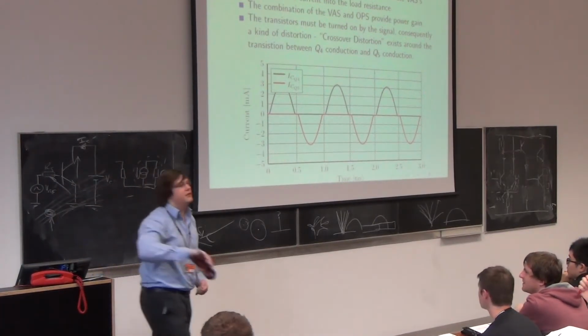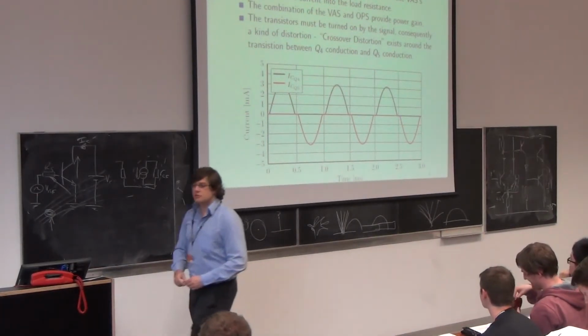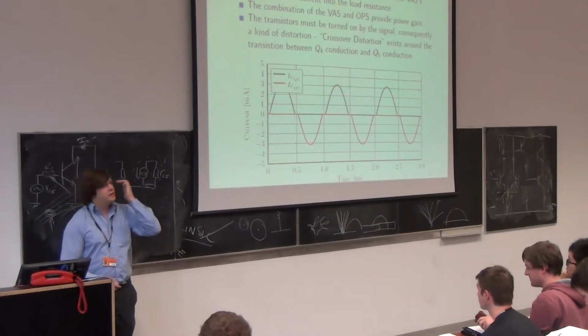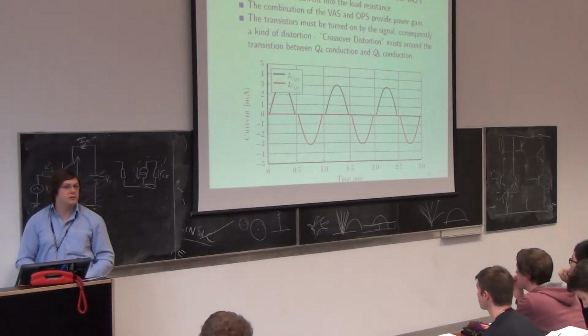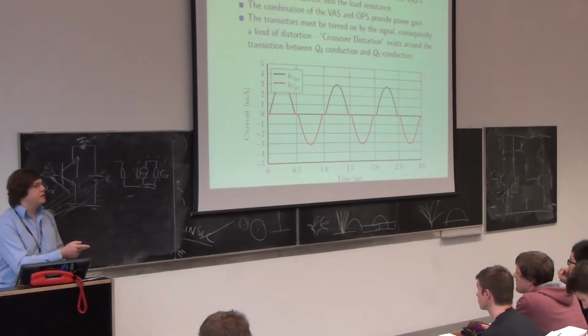Just in case you didn't catch that, both these transistors are emitter followers. As a consequence, their voltage gain is about 1, slightly less than 1 actually. If you're unhappy with that, it's in the prior lecture and it's in the handout I gave out as well.